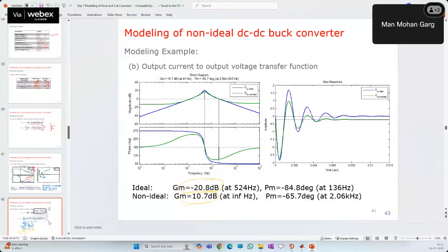This we will actually discuss in control, but because you asked now, what is this response? Let's say we have a simple converter, right? Whatever this transfer function is, it is for the open loop converter. Now this Bode plot, let's say I represent it as G(s), whatever transfer function we have, with some property, some gain margin. Now I'm simply making it closed loop with unity feedback, assuming no compensation and the sensor feedback gain is 1. So this is G(s) upon 1 plus G(s).